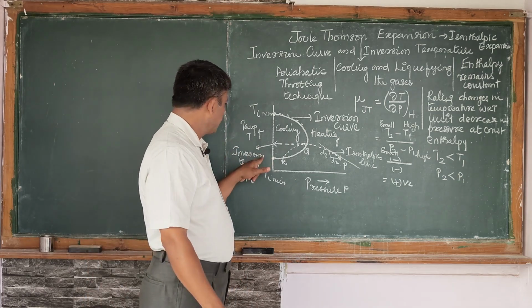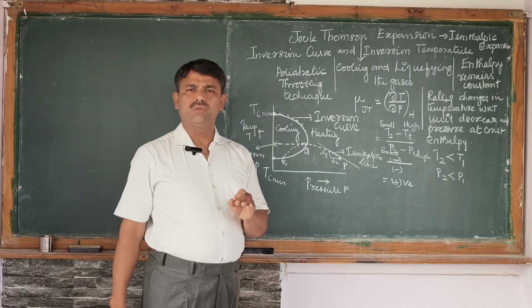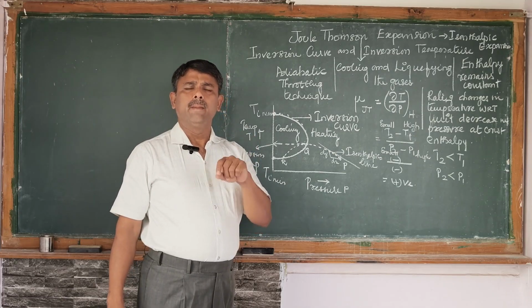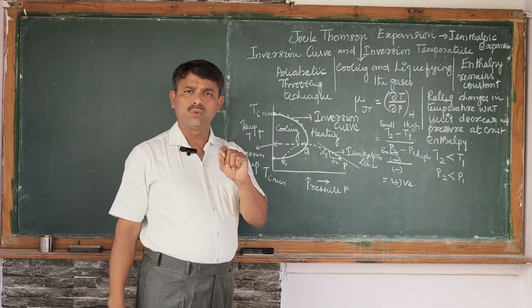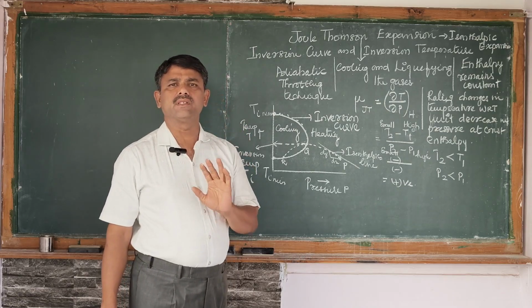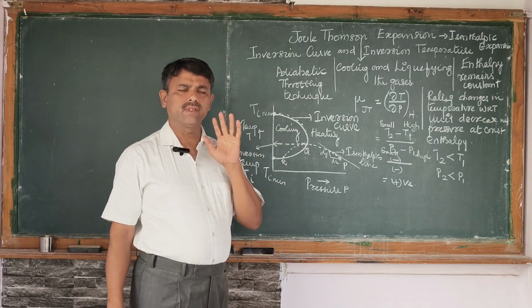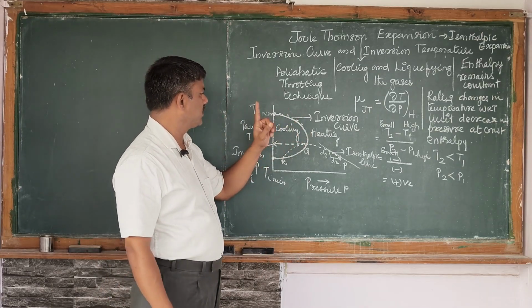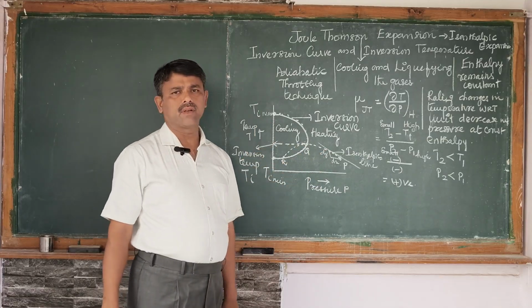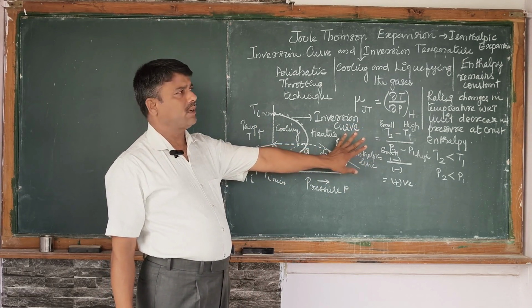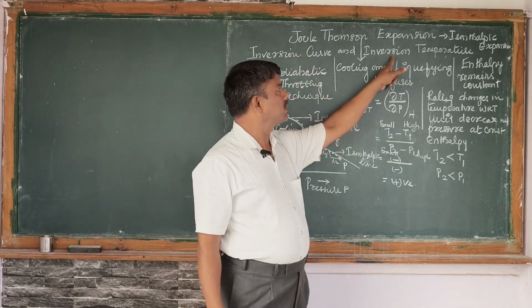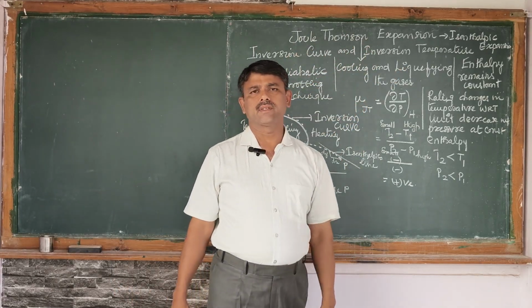Clear? Inversion temperature is very useful to us to find the minimum temperature to provide effective refrigeration. So: inversion temperature, inversion curve, isenthalpic curve. This is brief information on the inversion curve and inversion temperature in Joule-Thomson expansion.